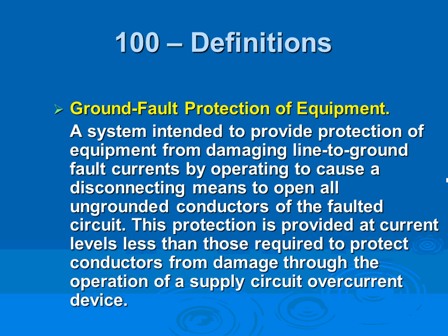The ground fault protection can be easily achieved by 3-pole, single pole, or 2-pole circuit breakers or fuses, up to 1,000 amp. Higher than 1,000 amp equipment, branch circuits, feeders, or services, the ground fault becomes low enough that it cannot be seen by the circuit breaker or the fuse, but high enough that it can create a fire inside your building.